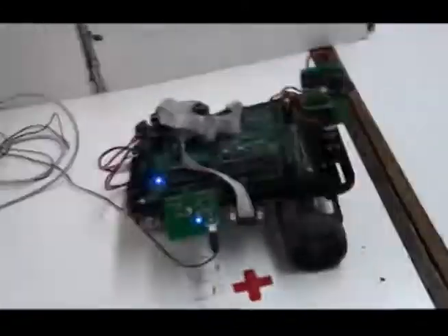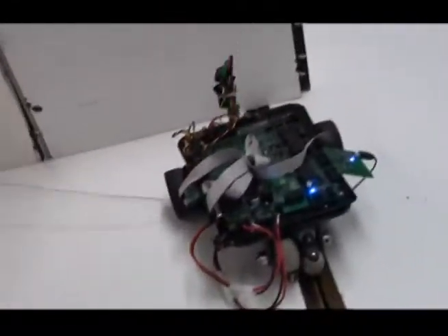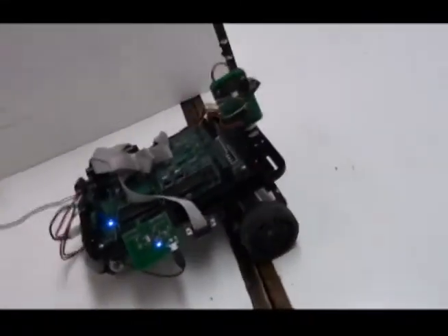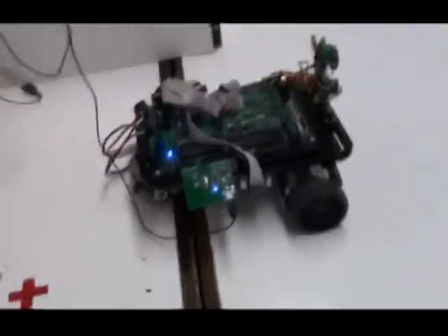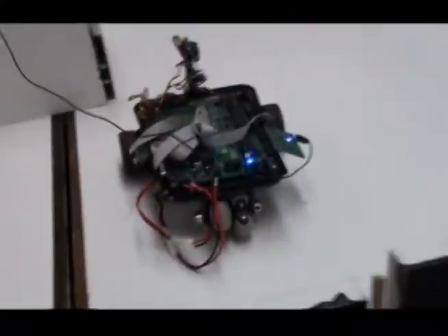Next, we're going to talk about the trajectory, which is the wavefront function. We implemented the wavefront algorithm to be able to navigate to the designated location we wanted. The task required us to move to the final goal using 5 waypoints. We would update the wavefront every time we scan and sweep, and the wavefront would go from the starting location to the waypoint, and every time it updates, the current location becomes the starting location, and it uses that to navigate to the goal location.